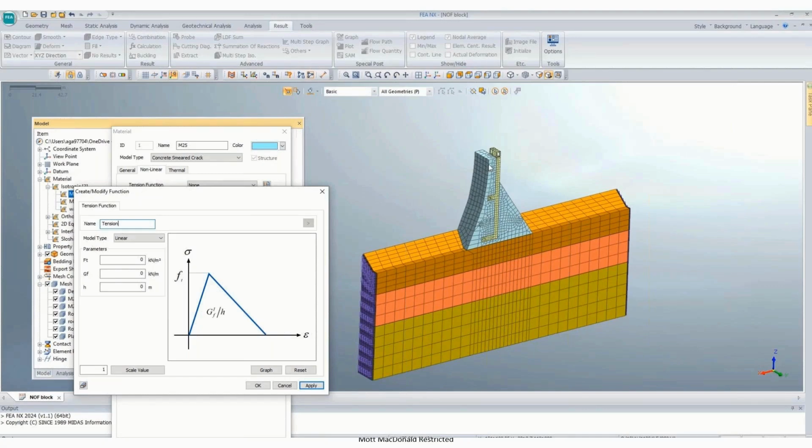Here we are actually simulating the entire dam, and uplift has been applied at the bottom of the face. If you want to include the permeability of the concrete, that is very low, I think 10 to the power minus 7 centimeter per second, something like that. You can provide it here, then perform a nonlinear analysis, and you will get the actual result, how much uplift you will get at different levels here.